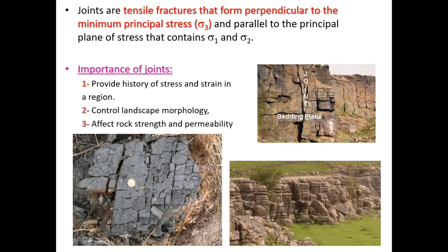Remember the example question in the lab, the very last question in the Mohr circle, Mohr diagram lab, we changed not the size but the location of the Mohr circle by injecting some fluids, and we basically pushed the circle to the left and made it touch the Coulomb failure envelope, and we failed the rock. That's the moment basically you form a new fracture inside the rock.